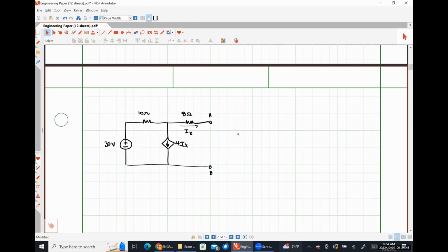So let me short out this guy again. And we're going to apply a voltage source here. Do we want the positive polarity terminal to be on top or on bottom? And I'm asking that, it is entirely an arbitrary decision. Does not matter which one we choose. Positive polarity on top. Okay. What magnitude do we want to use? Also, literally does not matter. 1. Okay.